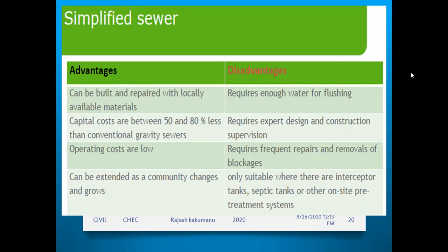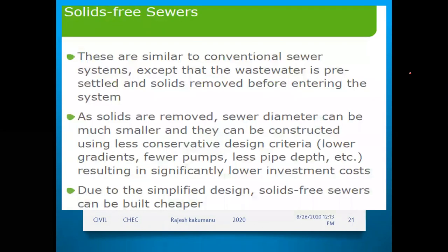See the next one, solid free sewers. This is the fourth one, solid free sewers. So what's happening in the solid free sewers? These are similar to conventional sewer systems, but the wastewater is pre-settled and solids are removed before entering the system.